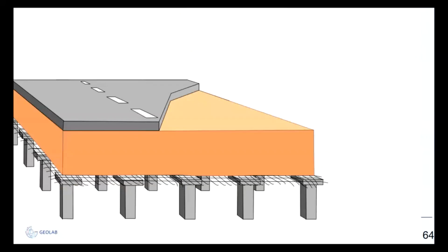In the research for this piled embankment, we were interested in developing a calculation model to predict the strain in a reinforcement. And here you see this strain. The reinforcement sags in between the piles because we have a cavity or a gap underneath, or just some consolidation underneath. That causes the reinforcement to get longer.